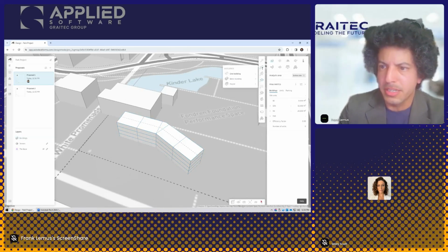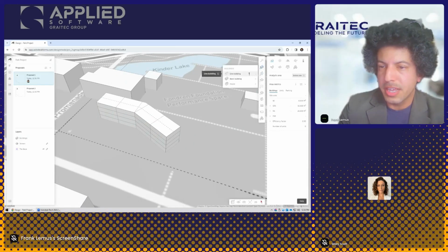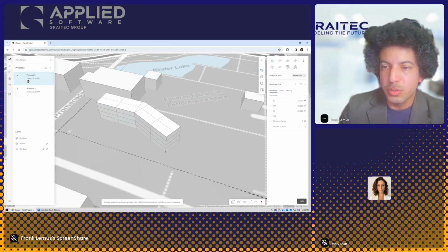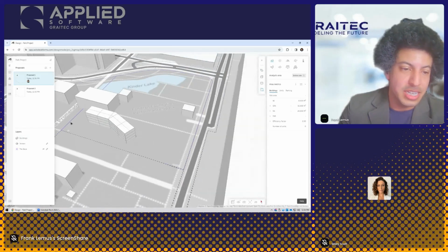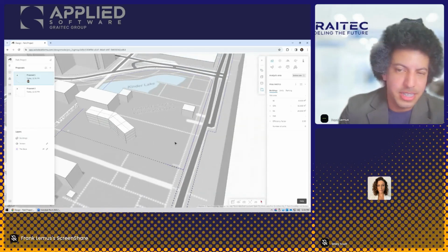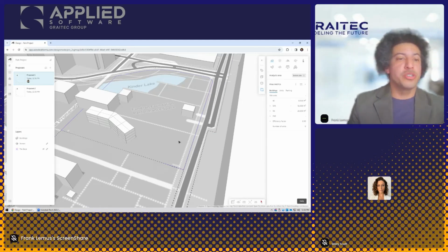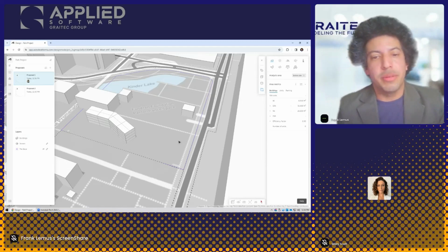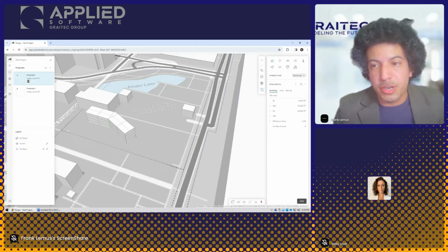So this is me creating a building based on line. If I go over here and I say basic building, see the shortcut B, then it takes me to these tools right here. You can select an element that already exists. Now you wouldn't use this here because see it's selecting elements like the boundary lines. That's not practical. You would be selecting something you would have imported yourself from AutoCAD, for example. Maybe you already have the footprint of the building. You just click on that to select the footprint. It does require that you import that CAD file first.